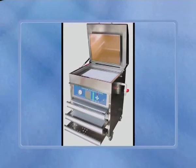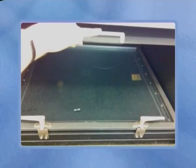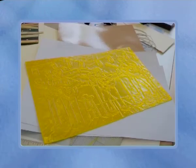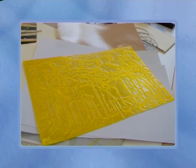Plate making uses light-sensitive polymer. A film negative is placed over the plate, which is exposed to ultraviolet light. The polymer hardens where light passes through the film. The remaining polymer has the consistency of chewed gum. It is washed away in a tank of water, followed by a washout process.